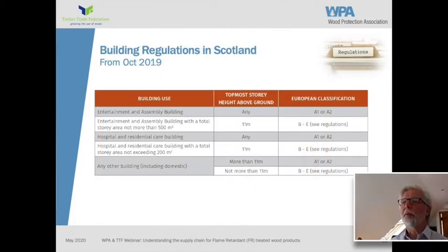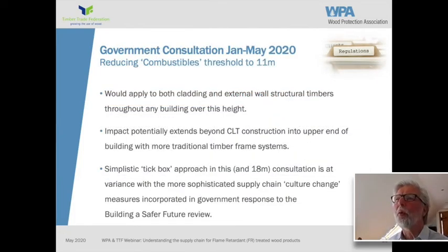Scotland's been slightly different, as it often is, and for them, essentially, when you distill it down, it's a very similar change to their building regulations, except they have taken the threshold as 11 rather than 18 meters. And we'll see that that's now become a talking point for the rest of the UK as well. I'll come back to that shortly.